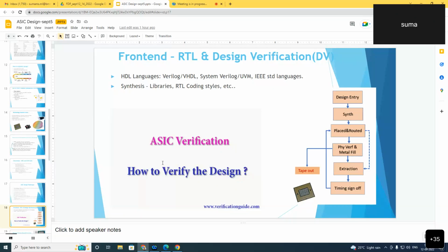So typically it will be in the .lib format. For example, if I say a logic library, it will be a .lib. When I say a physical library, it will be .plib. When I say a schematic library, it will be .slib. Synthetic library, .sldb. And of course, our Verilog module file will always be .v.